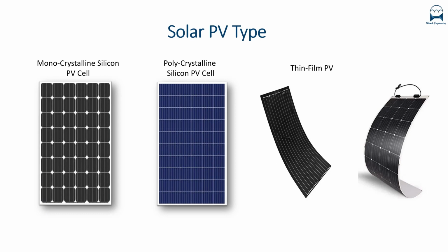Polycrystalline silicon PV cell. Polycrystalline silicon cells are formed by casting in a cuboid form ingot. The ingot is cut into bars and sliced into thin wafers, a thin sheet of semiconductor material, which in turn are used to create the cells. These cells are less efficient than monocrystalline.